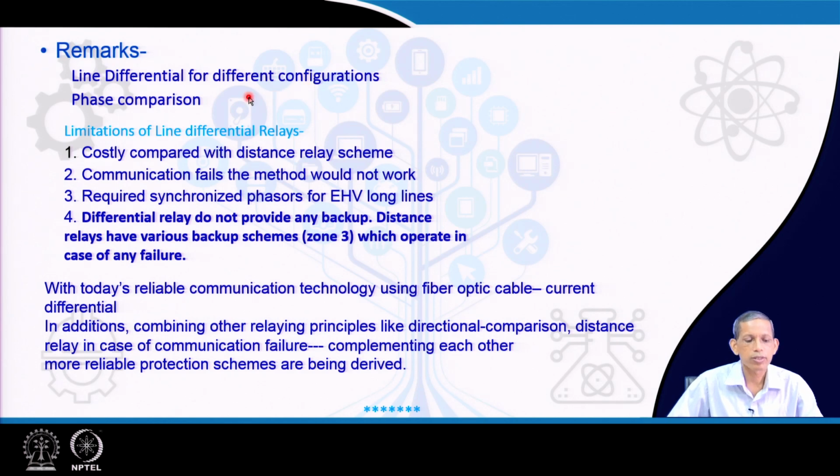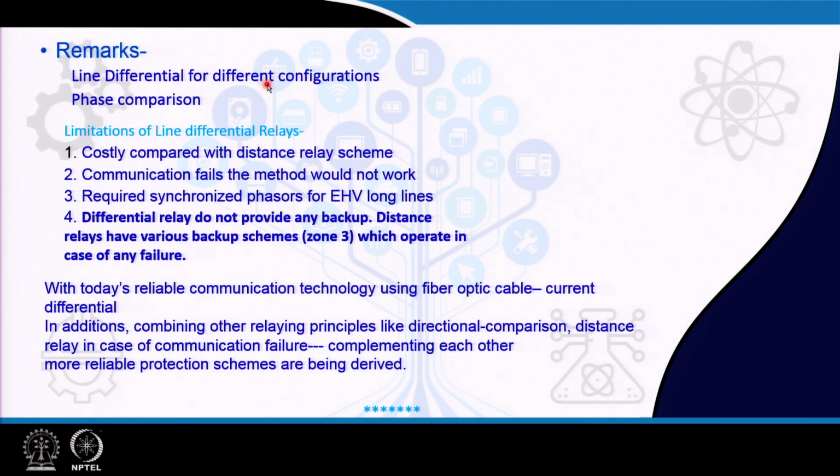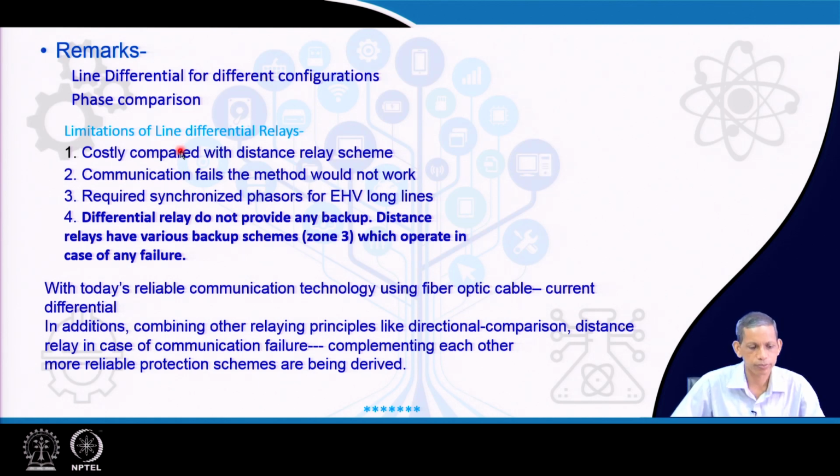So, with this we say that line differential protection is a very reliable unit protection approach. It requires dedicated communication for that perspective. We also consider that line differential protection can be extended to overall line and also transformer, and also tapped lines, multiple tapped lines can be accomplished for the line differential perspective. We also see how the phase comparison approach can be applied with a communication system arrangement for the line protections.